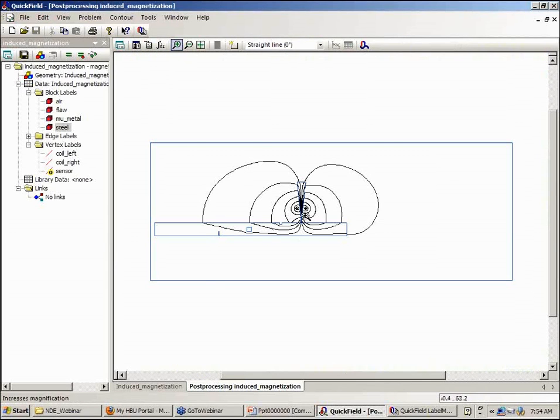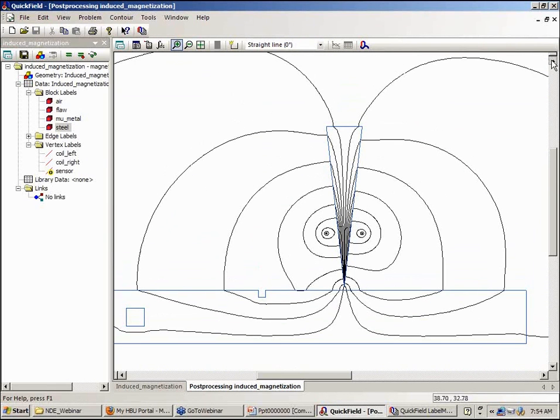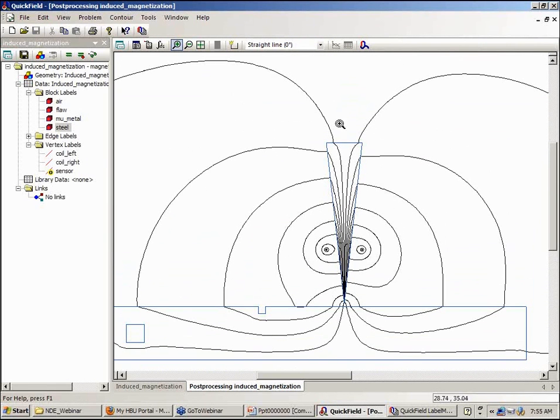I want to illustrate how the flux is channeled up the ferrite needle. So if we had a sensor here with poor spatial resolution, we could prove that since a small flaw being scanned under here will have changed the total flux that's being channeled up through the ferrite.